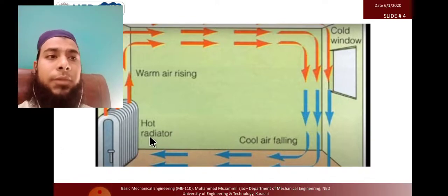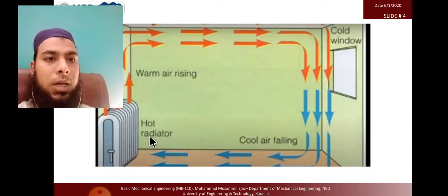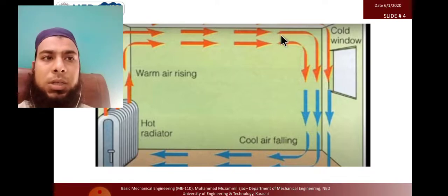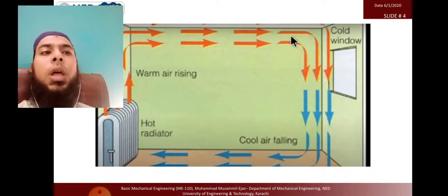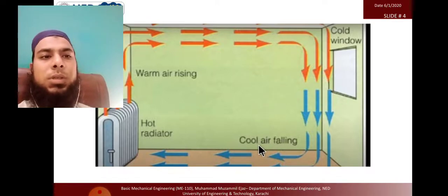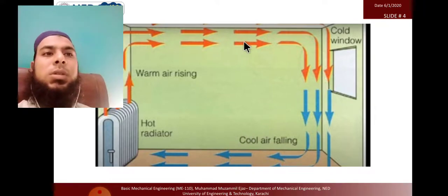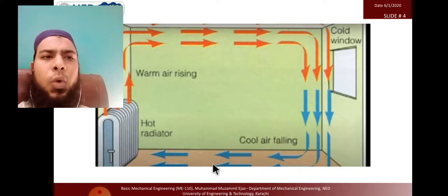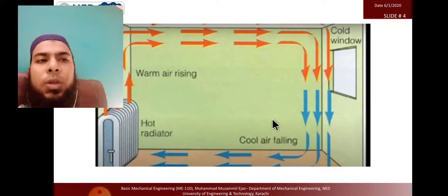But oppositely, if we need to place the air conditioner, we have to put it on the top side, because the air conditioner cools down the air, and the cold air comes towards the bottom, and when it strikes the human persons, it becomes hotter again and goes to the top side. So we have a natural convection flow, and in this way the whole room temperature becomes uniform.